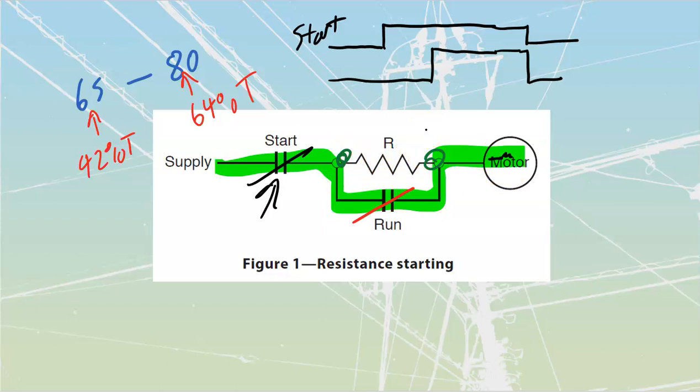It's also going to mean that we're going to need fewer controls placed in there, because if we don't have closed transitions, sometimes we can have problems from inductive kick, because we have these motor windings spinning through a field and we just get boom, these kicks that come back out of them.